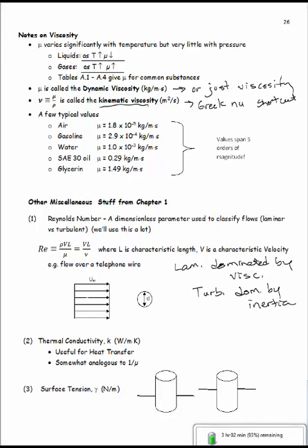And the incoming velocity of that wind speed is going to be your characteristic velocity. So what those characteristic lengths and velocities are depends on what your problem is, and you want to pick the most important velocities and lengths for that. So for this, we'll usually use a subscript to indicate what our characteristic length is. Reynolds number based on d is going to be u infinity d over nu.